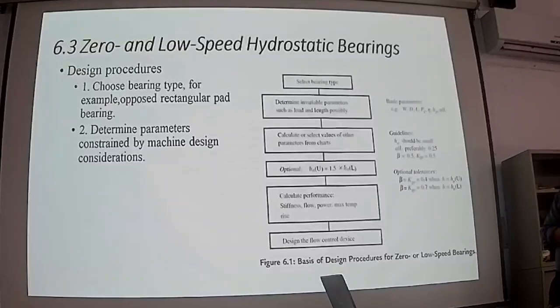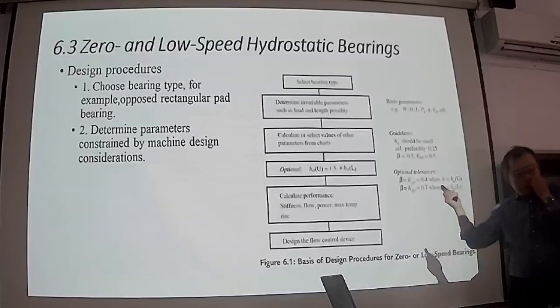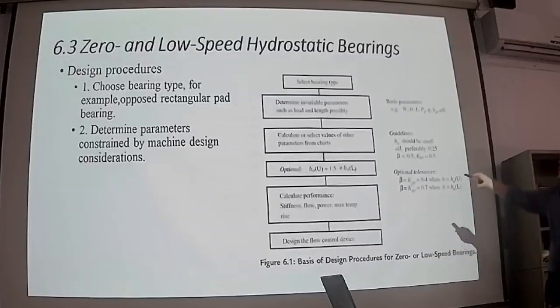所以基本上你如果有一些粗略的尺寸，你大概就可以去估算我的油腔大概可以承受多少的负载。那我就可以去考虑一下我的供油压力到底要多少，因为你有尺寸，是不是我就知道那个油腔的面积？You can have some rough estimation for your recess area from the diameter or length of the bearing.